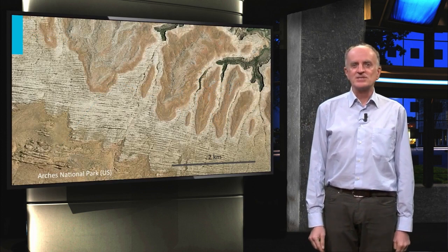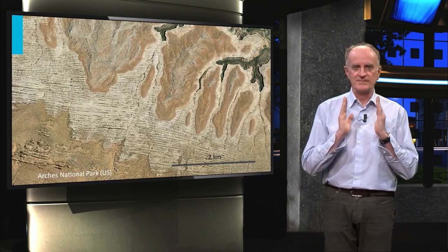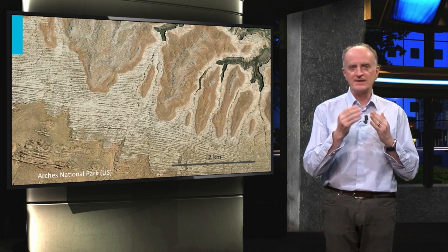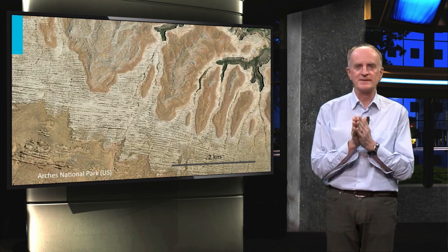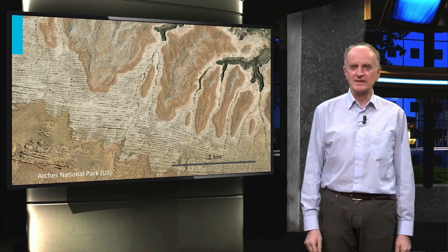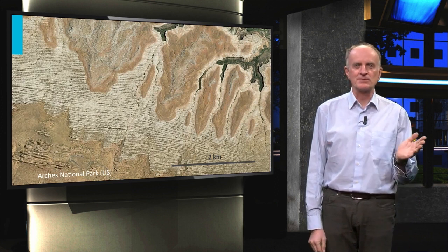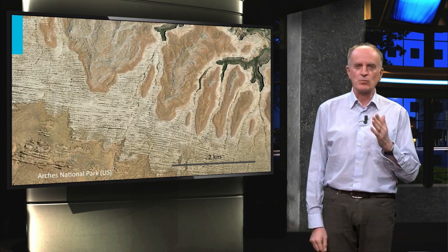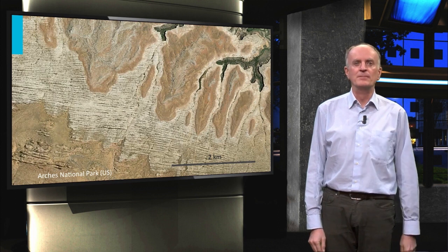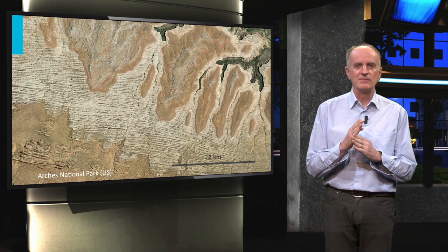Let us look now at the initial stage of deformation. The most common structures developing are joints. These are planar, very sharp features, often very long and with minimal displacement. Like in the case shown in the slide, joints never come alone. They come in thousands, generally nicely parallel to each other. Joints are often organized in one, two, or more rarely, more directional sets. In this case, they form networks, with fractures cross-cutting each other.